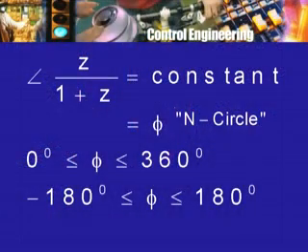You can calculate the location of the center and the radii of these circles depending on the value of the gain alpha or the phase shift phi, and you can actually draw a small number of them. When these ideas were introduced, of course, just as you have now graph paper or coordinate paper available, and I told you also that we have a semi-logarithmic paper available, people prepared and sold charts containing these M and N circles.